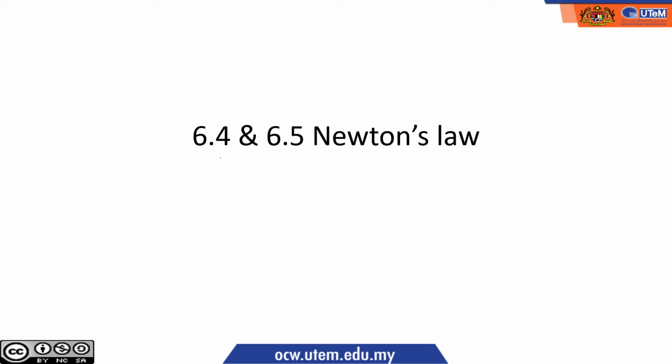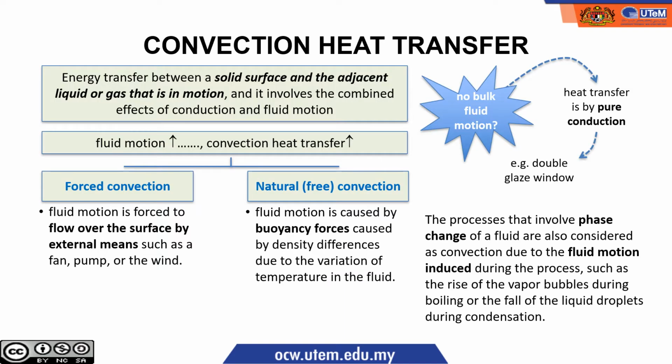Introduction to heat transfer is about heat transfer by convection and Newton's law. Okay, convection heat transfer. What is it? It's an energy transfer between a solid surface and the adjacent liquid or gas that is in motion, and it involves the combined effect of conduction and fluid motion. So there must be conduction and fluid motion.